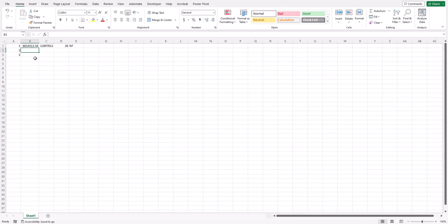Then you're just going to enter in the other values here for point number 2, so 681421.57. I'm tabbing over to the next column for the easting of point number 2, which will be 1189764.18. And I'm going to tab over for the elevation, which will be 23.24. And again, nail found. And I'll come down to number 3.